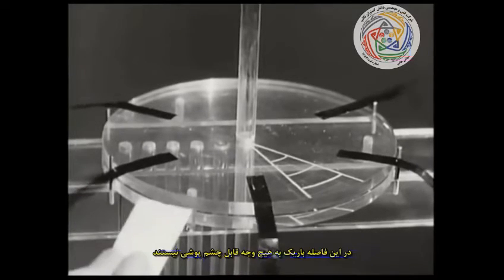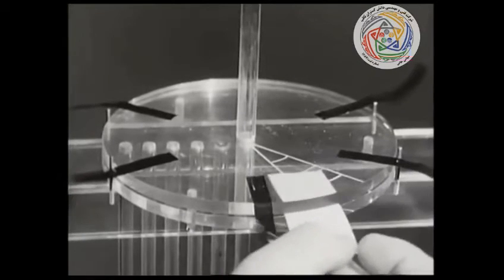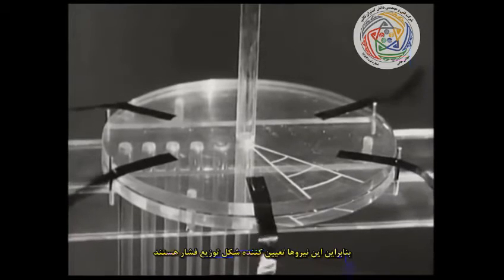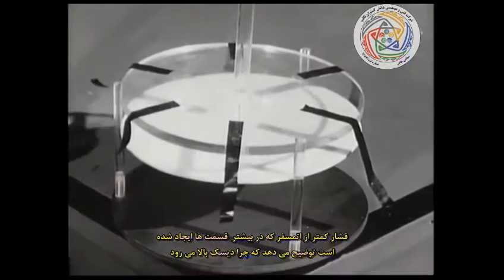Actually, the viscous forces in the narrow gap are by no means negligible. But in this particular experiment, the mass acceleration forces are generally larger than the viscous forces, and so they govern the shape of the pressure distribution. The subatmospheric pressure over most of the area explains why the disc is lifted.